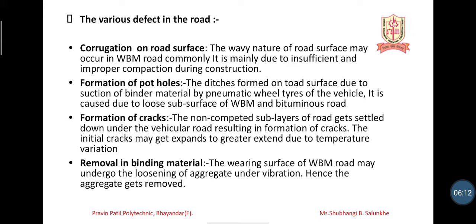Then the next is removal of binding material. The wearing surface of a WBM road may undergo loss of aggregate under vibration. Hence, the aggregate will get removed. Why has this binding material been removed? If a binding material doesn't have proper binding properties, then obviously the material is going to be removed.